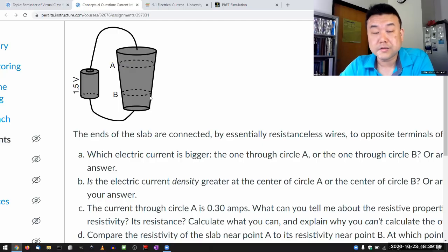So when you apply Ohm's law over that slice of the conductor, the current ends up being the same, because the resistance of this slice is lower, but the voltage difference across the slice is also lower compared to the resistance here and the voltage difference across that slice.